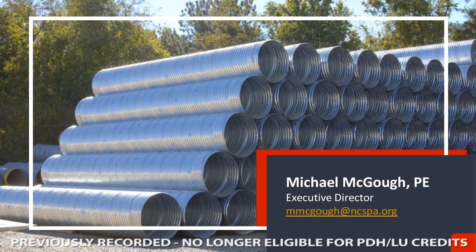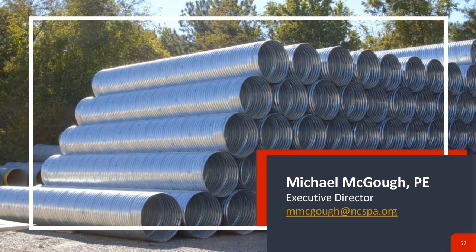In essence, what you're talking about are a couple things. One, if you're going to use a metallized coating, would be the use of a geomembrane over top of the pipe or the structure to shed those chemicals away, or a polymer coated pipe would also serve that same purpose.